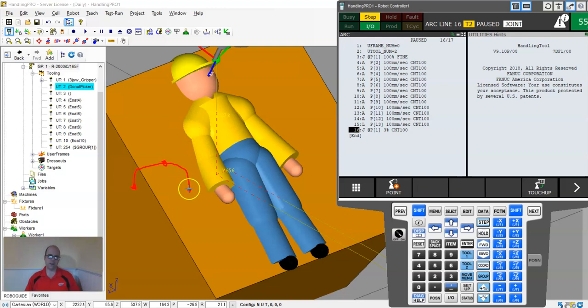It's because it may not change its location or complexity. So say we've got a sine wave type of thing that looks like this, you might need to stack points. You just make life a lot harder on ourselves. But if we use a circular arc command, which is the A command, which you can see right here on the teach pendant, this will take into account all the inflections and the changes in the circularity, the inflection points. That's the word I'm looking for. So that's how we're going to do that.